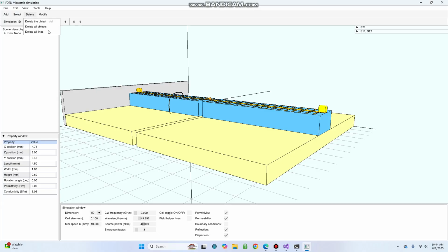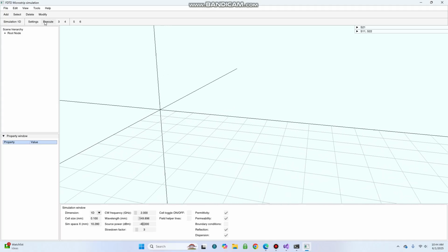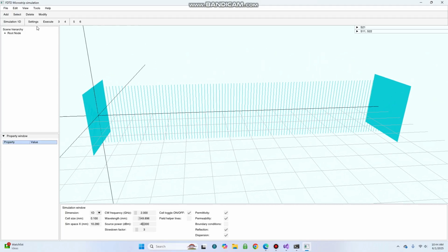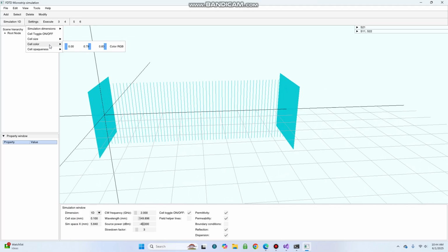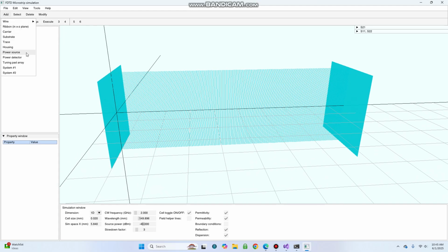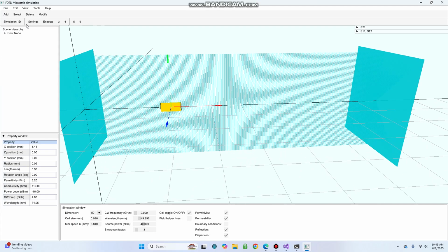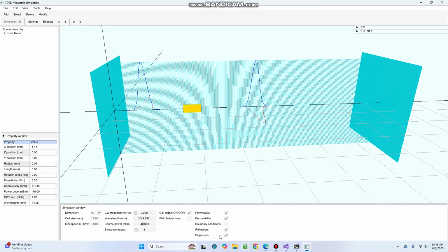What I have implemented is a 1D method, and in it you can see it's similar, but the wave is actually in 1D. So if you decrease the simulation dimension and decrease the cell size, and you put the RF source in here, you can actually run the simulation. So what I'm doing here is I'm generating a Gaussian pulse, and it spreads in both directions.